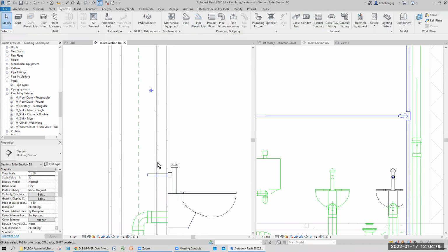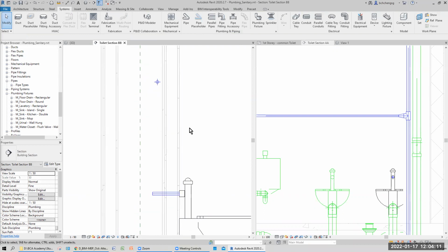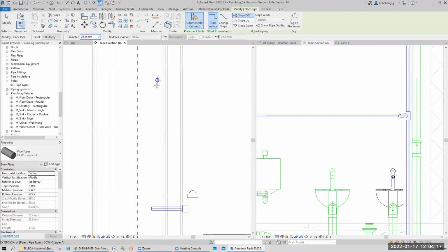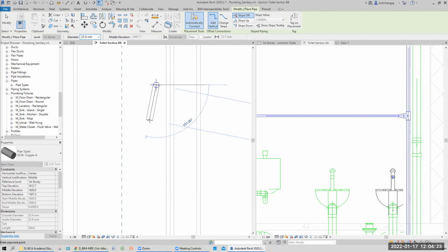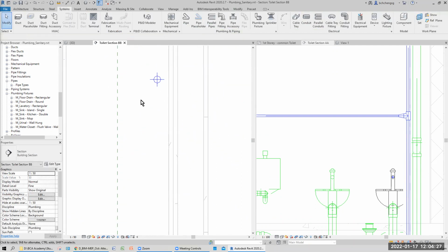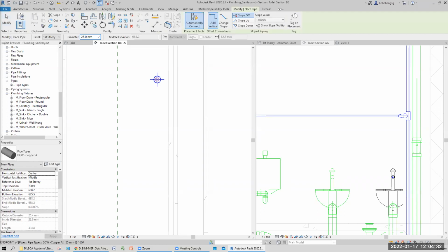Okay, how to align the point exactly here to the connection. Zoom in, use the alignment tools. So AL, where's the reference? Here. All right, click once. Reference, RP, AL, align when you're snapping it.